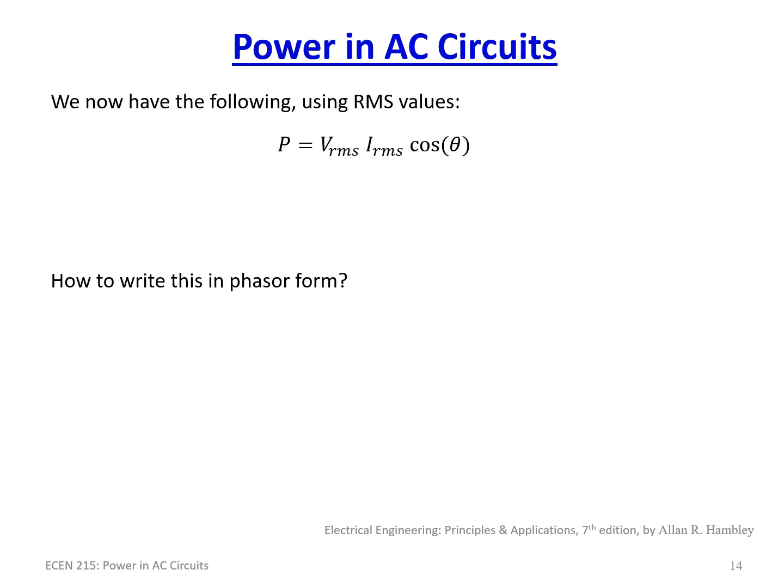So we've been looking at all this, and so far we have this equation for power: P is equal to V_RMS I_RMS cosine of theta. So this is a real power. And we know that power is equal to V_m I_m, where these are the voltage and current magnitudes, divided by 2, times cosine of theta. So these are equivalent, and we know that.